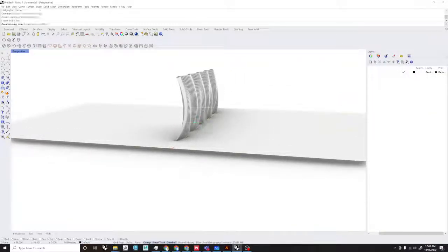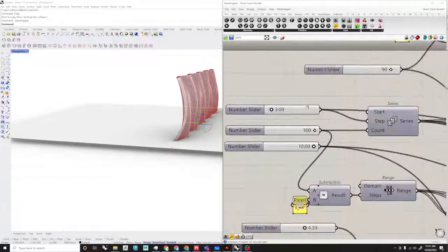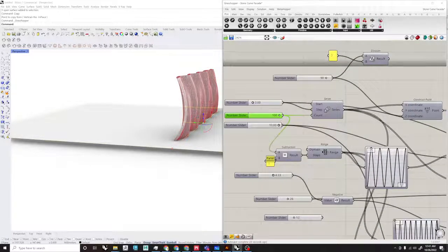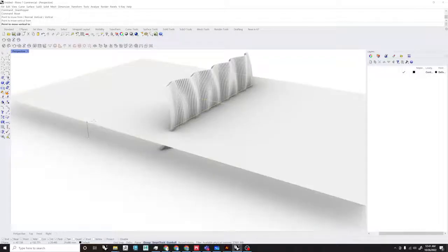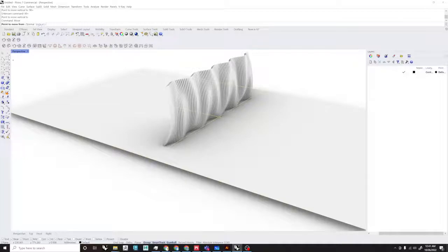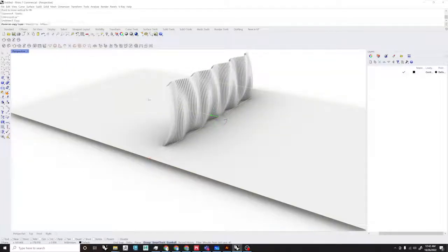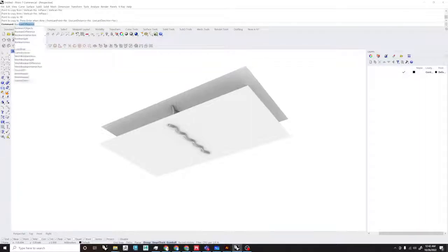And now we did it by 10. So all we need to do now is, what was that total height? Total height is 90. So I just need to move it into Z 90. So move vertical 90. Oh, oops, I already messed up. My bad. I shouldn't copy. Do 90. And then do a Boolean split.